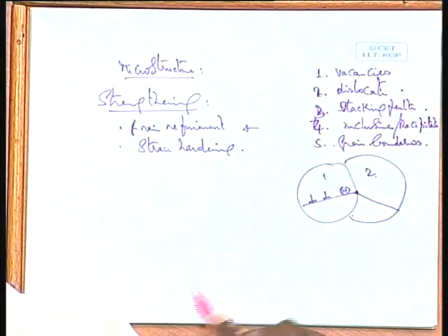So this plane ends here, and as I mentioned, the grain boundary always has a certain thickness, and within that thickness the atoms are arranged in a random fashion. There is a kind of disorder at that boundary, and because of the disorder, we cannot imagine any plane really in that boundary. You cannot say there is continuity as far as the atomic plane is concerned. The moment it comes to the grain boundary, there is an abrupt discontinuity, and because of which the dislocation cannot move further in that plane.